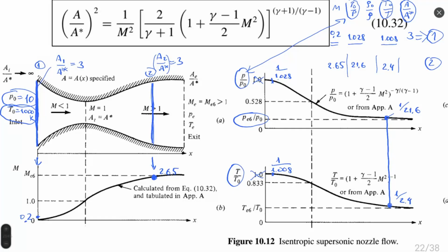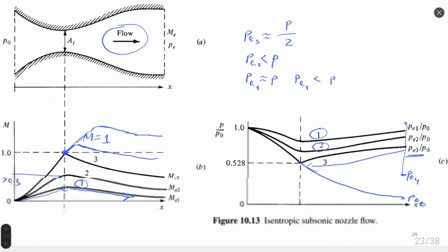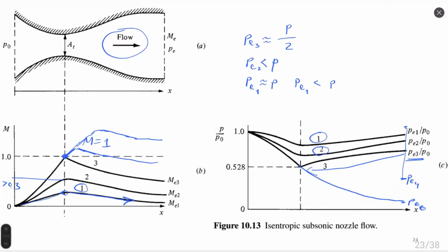If energy is not enough for continuous acceleration, we have a figure like this here, which is divided into 2 distinct cases. Case 1 and 2 correspond to subsonic flow inside the throat, and case 3, 4, 5 correspond to acceleration in the supersonic part and then deceleration.